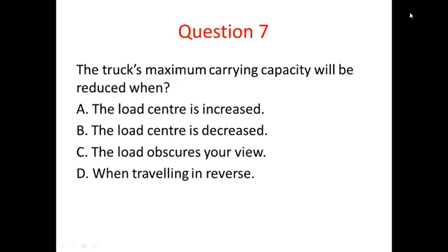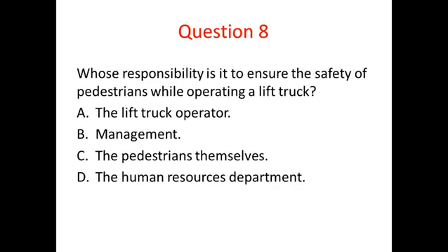Question 7, the lift truck's maximum carrying capacity will be reduced when? So when the load center increases, i.e. when the load moves towards the tips of the forks, the truck is able to carry less weight at that point. So the answer for that one is A. The load center increases.